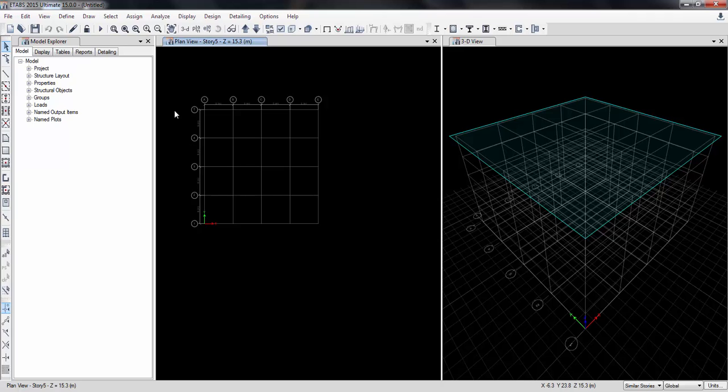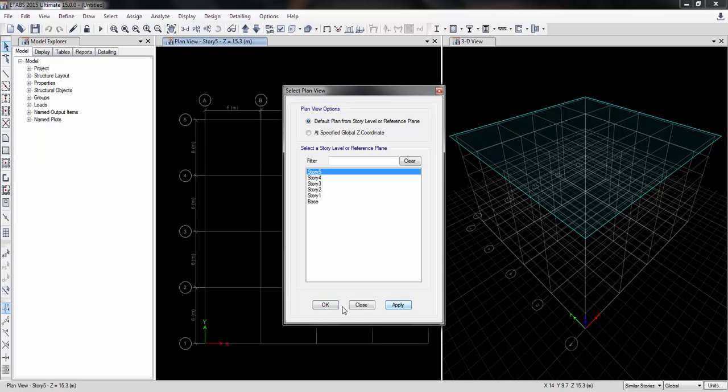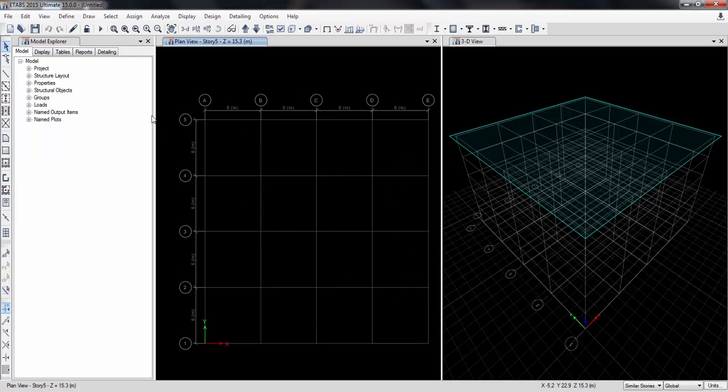Now we are going to draw. So, we are going to draw now all the beams and slabs. So for quick draw beams, use this one. I'll go to draw command. In that you will find draw frame and beam, and in this select as beam, and it should be continuous.